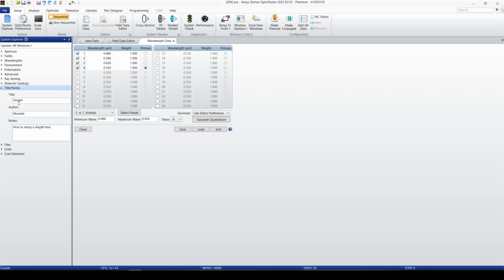And then the file is, whenever you want to have coatings data, you want to change the coating, you can have your own coatings data, and then reload. Whenever you change it, we can reload it, and the new data is going to load into Zemax. But right now we are not going to change that parameter.